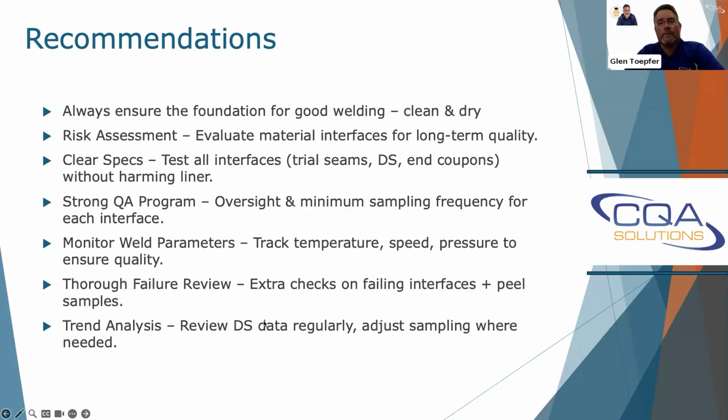That's what I was going to say about the trends too. Look at the trends. One of the projects we were auditing, I started looking at the fusion welding and the extrusion welding, and I saw that this one operator failed on every piece of equipment he ever touched for trial welds. Now he passed his destructs, but it was random on that project whether they were hitting them. They weren't targeting them, and it wasn't really good CQA oversight. When we were out there doing our audit, they were being more influenced by where the installer wanted the samples taken than what they should have been.